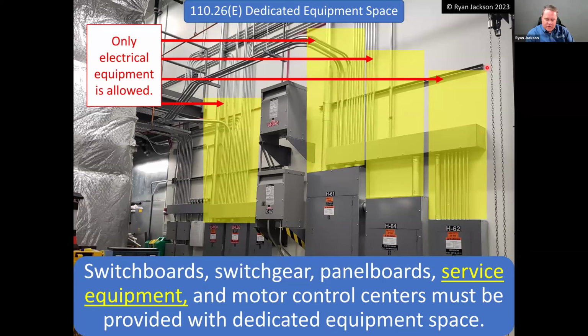So in 450.21, for big transformers over 112.5 kVA, you're supposed to have a 1 hour room, but there's two exceptions to it, and they're specific to the transformer, and you almost always meet those exceptions. Modern transformers, the way they're built, they pretty much always get you out of those exceptions. So very, very seldom do you need it.